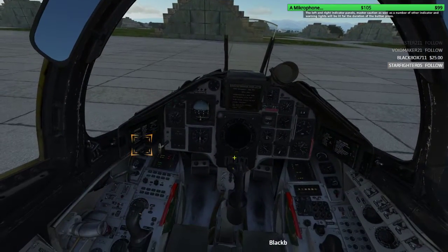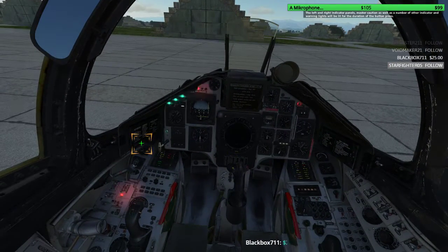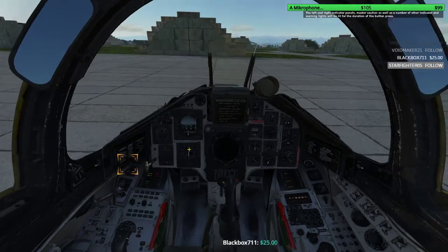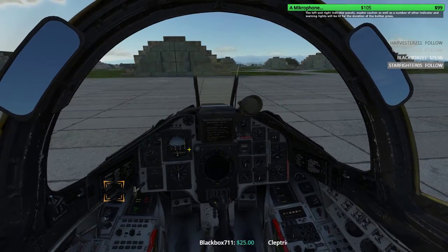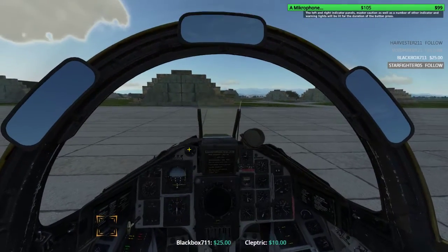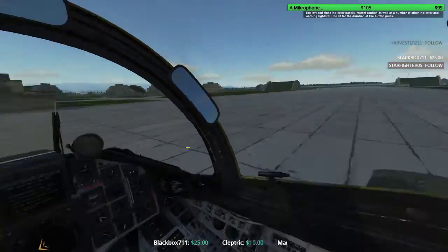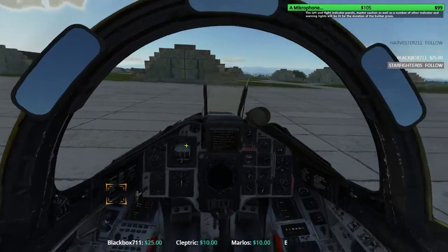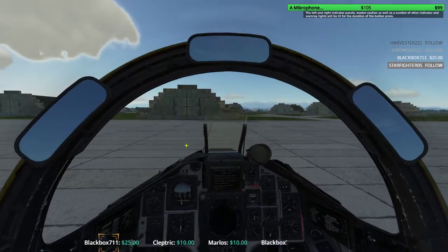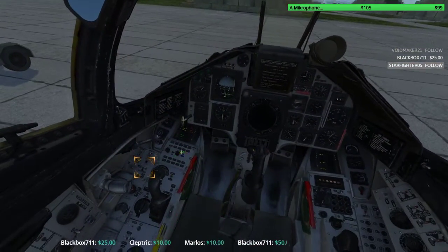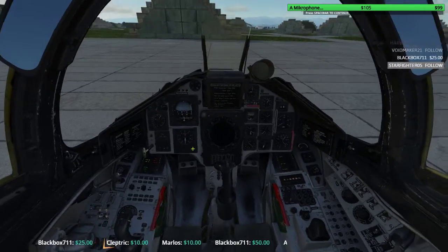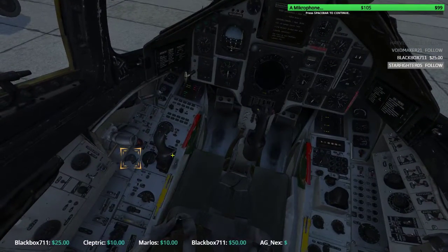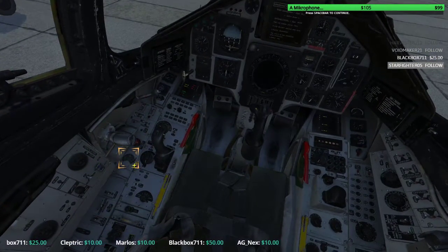Press and hold the warning panel test to test that all the warning indications function. The left and right indicator panels, master caution, as well as several other indicator and warning lights will be lit for the duration of the button press. Turn on the main generator. Then, center the autopilot yaw correction dial by setting it to 0.